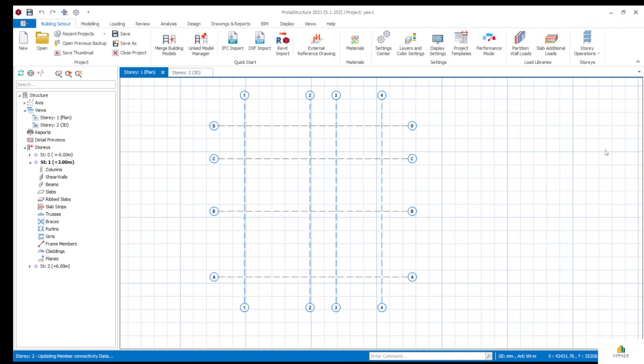Then edit story. Let's click on the edit story. So at the edit story too, you see the same thing as we already see at the remove one, right? So you see this side. So you see first story bottom level zero, foundation depth, right? So it's asking you your foundation depth. So let's say your foundation depth from your ground floor, which is the story zero, to where your foundation is, let's say 1,000 2,000. Then footing label, let's say F, right?